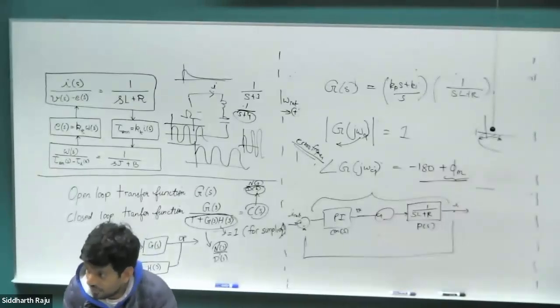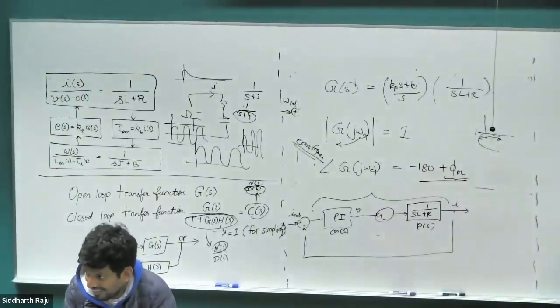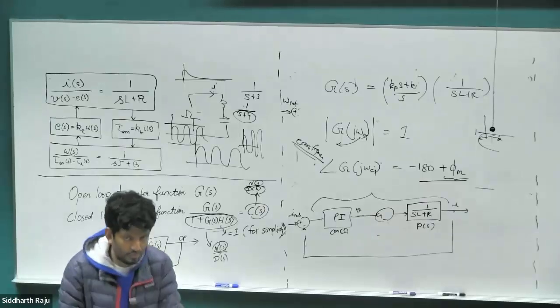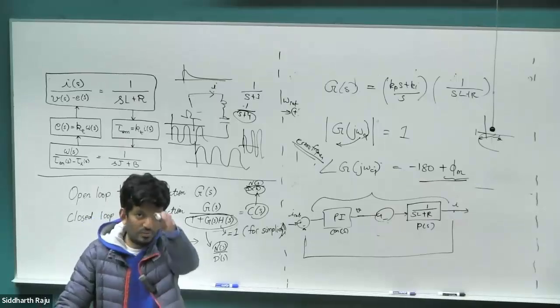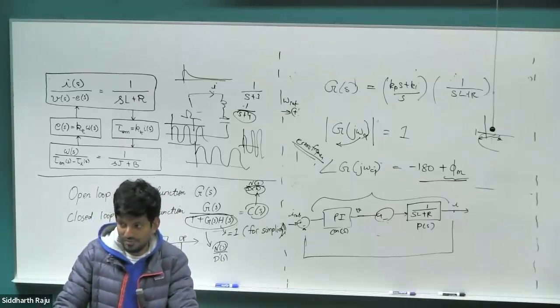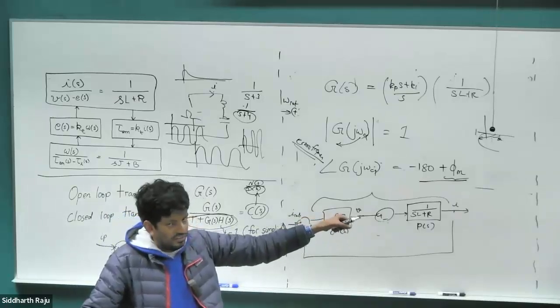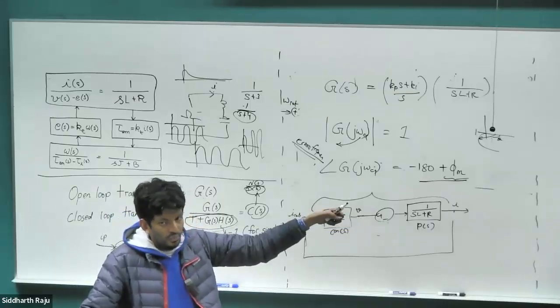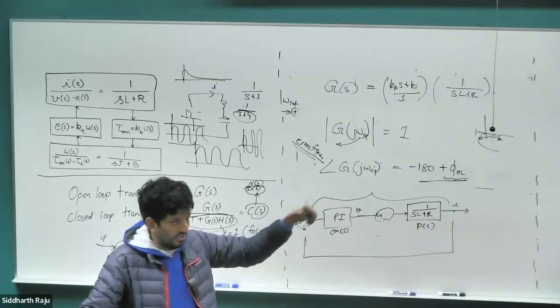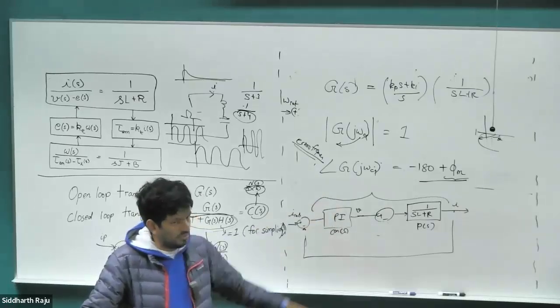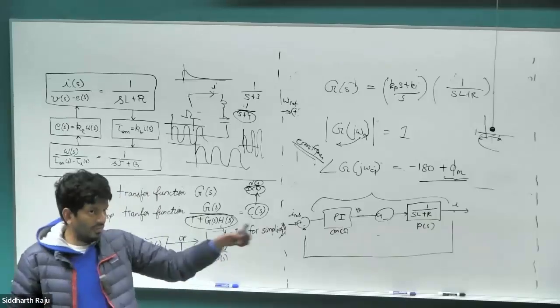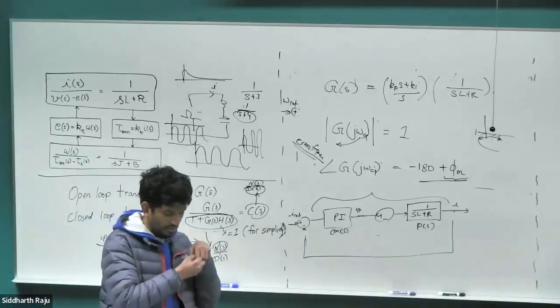Yep, you want to answer that question? Like if there's any disturbance that could affect the position, you might want an integral term or something like that. Right, perfect. There is no disturbance in the case of the camera right there. Once the theta reference reaches the theta feedback, the error is zero. You do not want any speed in the motor once the error goes to zero in case of position control. So in those cases, you can just do with a P controller, but in case of disturbances, you would need an integral controller as well.